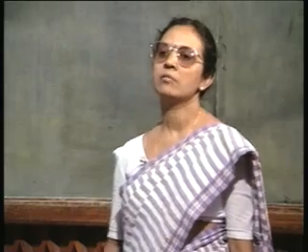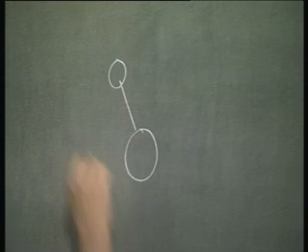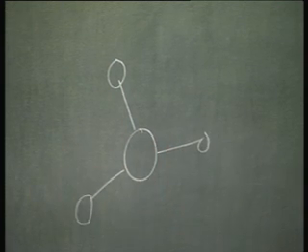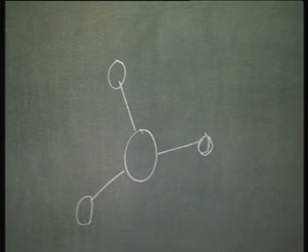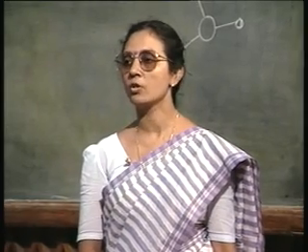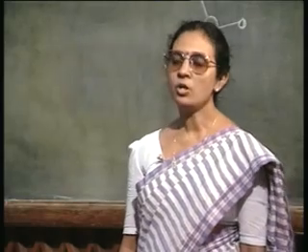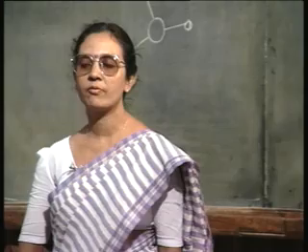For example, take any crystalline material. In the bulk of the material, it may be nearly ideal, that is, there may be a regular array of atoms. What about the surface? The surface means there is a loss of crystallinity on one side. Inside this diamond structure, each atom is bonded to its 4 nearest neighbors in a tetrahedral structure: 1, 2, 3 and the fourth one going inside the board. But not so on the surface. On the surface some of these bonds are not present. We call these dangling bonds. These bonds are dangling in space. So, any real crystal is far from ideal.